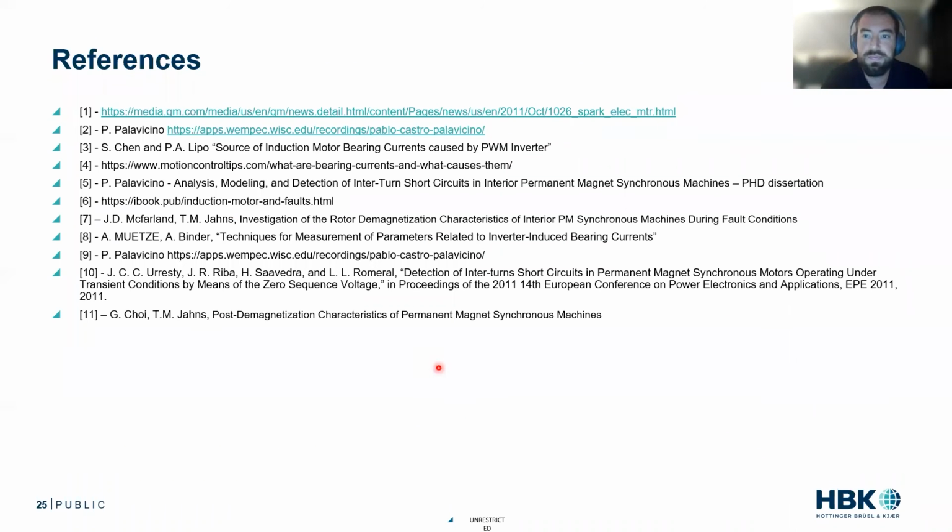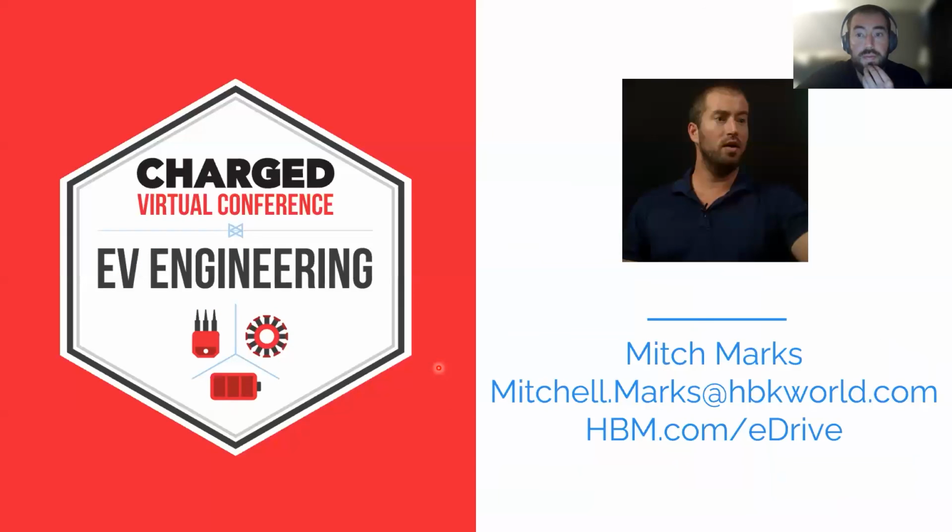Someone is wondering about ambient temperature and the effects it might have on demagnetization and battery life. I can't make any comments on battery life. Sorry, these slides will be provided to you, so I'm not going to linger on this one. They'll be sent to you. Ambient temperature can just drive the total motor temperature up, so I think that's the big effect. With turn-to-turn shorts, you're obviously worried about the winding temperature, but that should be in the housing, and there should be a cooling system involved. If it's a passively cooled machine, then ambient is a big deal. If the ambient is around the enamel thermal limit or the magnet thermal limit, then yes, it's a big issue. But you're mainly worried about the magnet temperature and the enamel temperature.